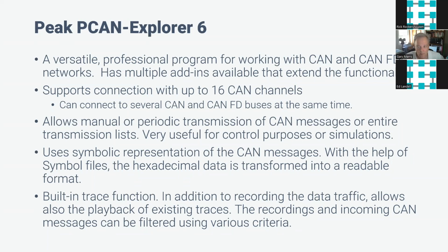You can add symbols to make those CAN messages and their payload a lot easier to read than just looking at hexadecimal data. And then there's some really cool add-ons. There's a plotter add-on that can graphically display the CAN data from your CAN messages in real time. There's an instrument panel for arranging a variety of displays, controls, switches, and connecting those to your CAN data. And then there's add-ins that enable native protocol support for protocols like CANopen and J1939. I'm going to show you a couple of these add-ins.